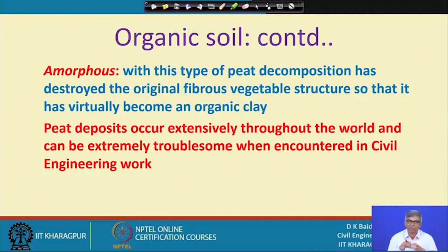That means it is not only decomposed, the particle size becomes so small, it is like a clay, and when this organic clay forms in a large volume at a particular site, it is dangerous, but its behavior is very much unknown, and a lot of volume change will take place, because of that it has to be handled very carefully. So, peat deposits occur extensively throughout the world and can be extremely troublesome when encountered in civil engineering work.